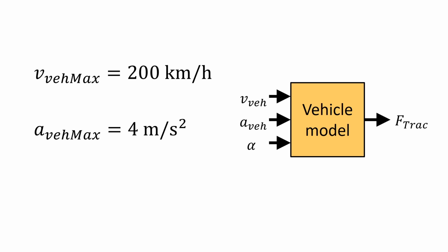For safety reasons, a vehicle should be capable of decelerating as much as the road friction allows, about -10 meters per second squared, but since that force is provided by the brake system, it is not a part of the powertrain requirements. The road gradient is most of the time below 20%, but to handle extreme cases, our car shall be able to climb 30% gradients. This analysis only deals with the requirements when driving forward. Requirements for performance in reverse gear are different, but can be analyzed in the same way.